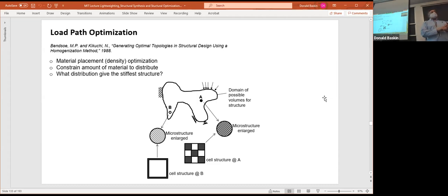Assuming the density starts off at 1, you calculate out the stiffness of this whole thing based on finite element analysis, or the strain energy, or the strength. And then what you do is you start saying, suppose that the density isn't a full 1 for every element. We have to be more strategic about where we place our mass in order to get the stiffest, most efficient structure. So this is where the numerical optimization part comes in.